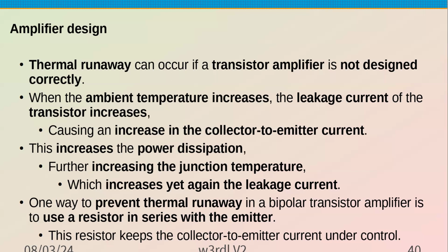The same thing is true for any metal. In the case of the semiconductor, with the current increasing, the heating effect causes additional current flow. So the more current, the hotter it gets, the more current, and it's called thermal runaway. So that's one of the things that you have to prevent in a solid state power amplifier.